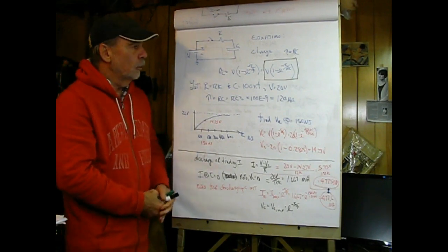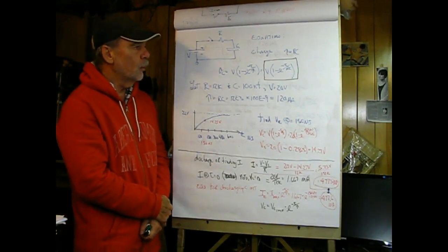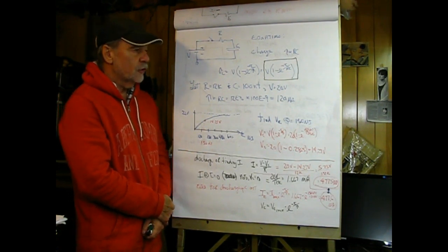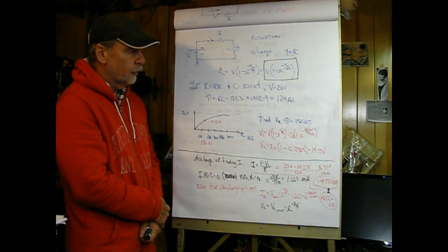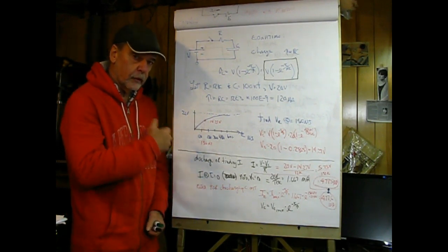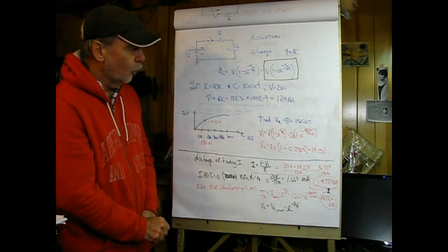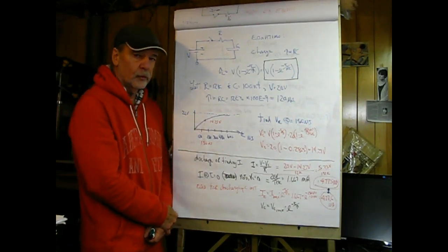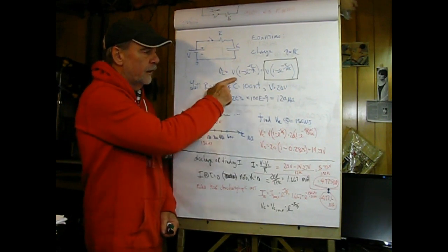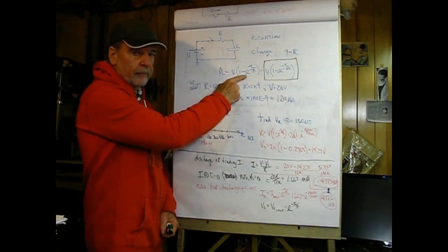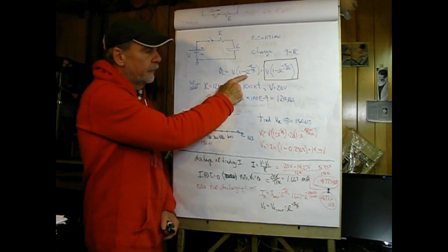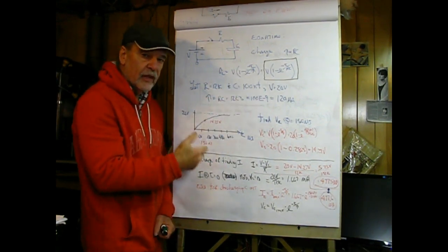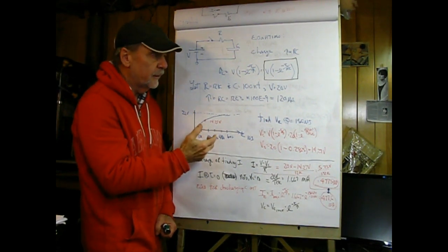So yeah, mix a little math in here, and what we know is that the time constant equals RC, and for a charging capacitor, and under certain circumstances, this can also be used for currents, and that's explored in AC circuits a little bit more. But the defining equation, one which would be very good to learn, is V times the quantity 1 minus e, the natural number e, to the negative t, that's the physical time, divided by the fixed time of the components, which would be tau.